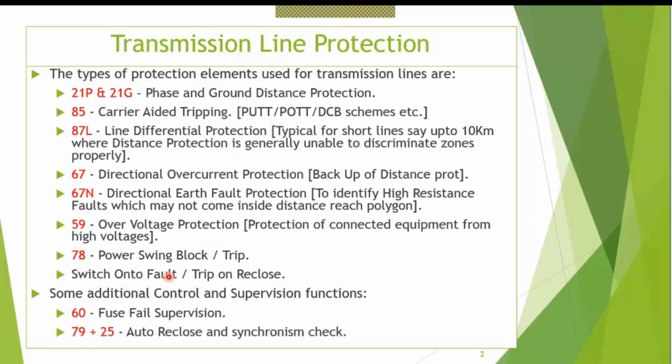We also have a switch onto fault or trip on reclose protection, which deals with closing a line onto a fault. There our memory voltage and those things are not available. Probably the voltage will not rise fast enough for the zone 1 or zone 2 protection to operate. So we have a separate protection which is applicable only during closing.